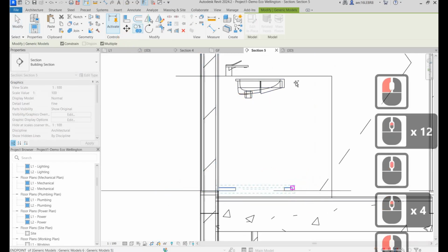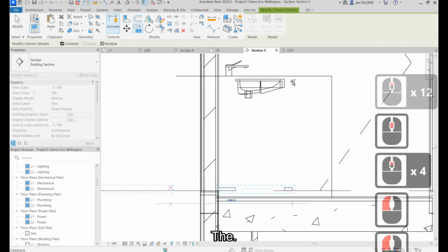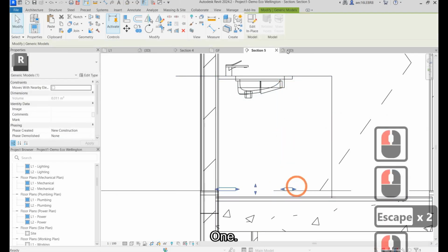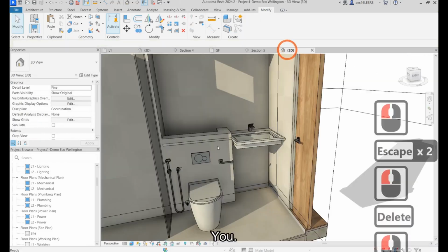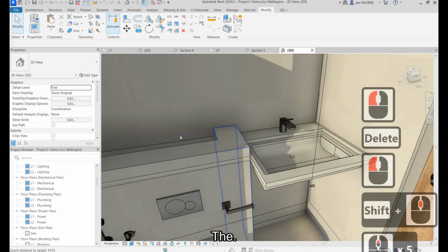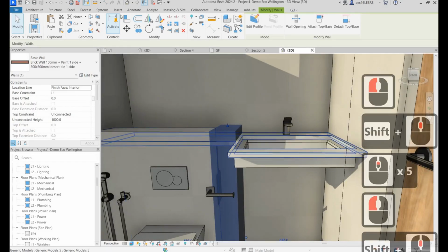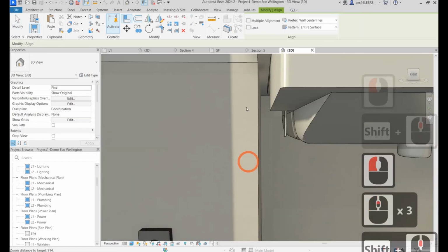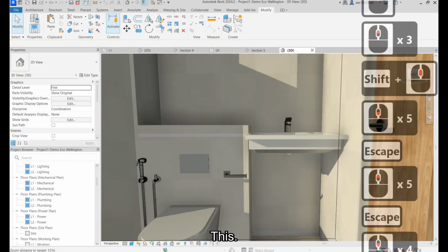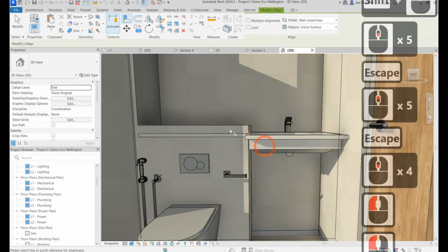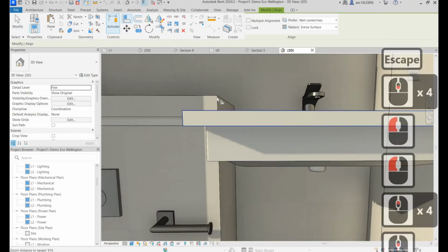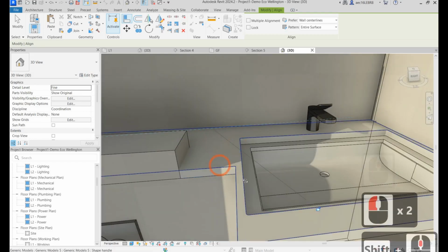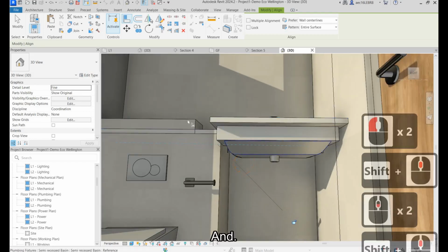Copy function. Okay, remove the constraint, place to here. Delete this one. So from the 3D view, you can see that the height of your brick over here, you cannot access this countertop. So first you need to align this, align to the bottom surface. Okay, lower it down. Basically, of course, let's lower it down like this.